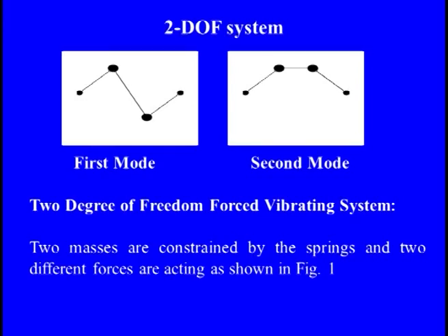So you can see that in this first mode, when we are saying that they are absolutely in the opposite phase, both are diagonal to each other. One is going down, one is going up, one is going up, one is going down in the first mode. While in the second mode, you can see that they are in phase, that means both are coming together in the downward direction or upward direction. These are the two masses connected to the two springs; they have the same relative movement in the second mode or in the first mode, irrespective of whatever it is.